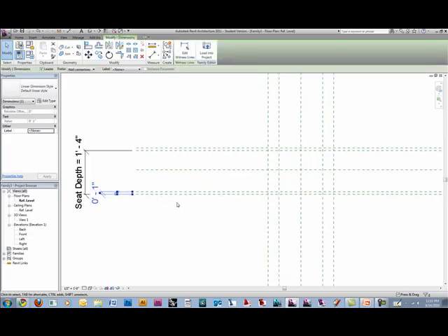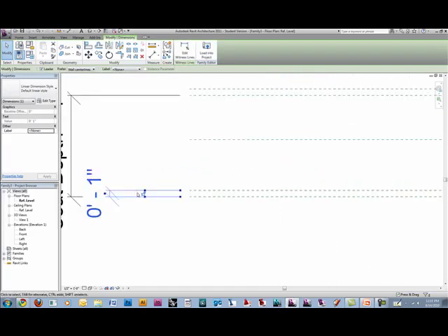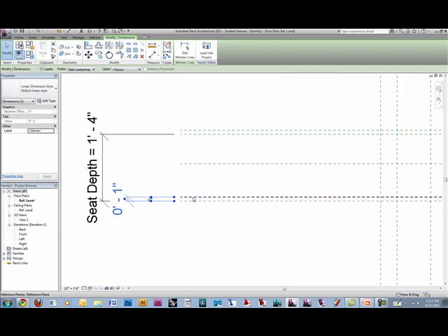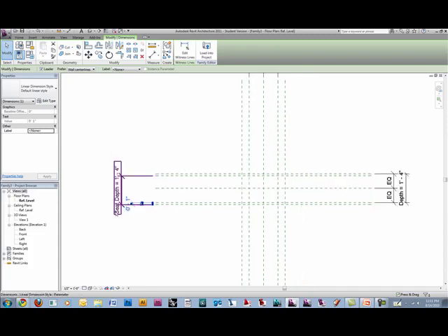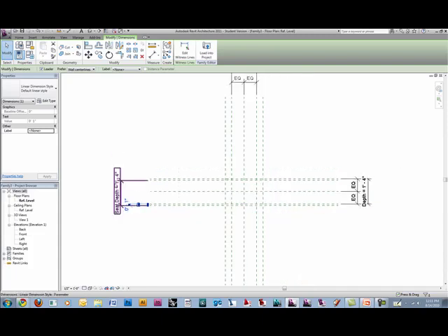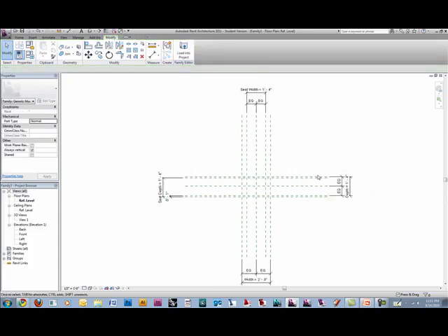I do think I want maybe a 1-inch overhang, and this is where the lock kind of comes in, because if I always want this to be a 1-inch overhang, I can just lock it. I don't have to add a parameter to it. So they don't have to go through and type all that stuff out. I just get it where I want it and say, alright, done. You could also do the back if you felt like, but you can't do the front and the back, because then you're double constraining all the lines, and then it'll say you've over constrained it, and it'll honk at you, but you'll learn as you go.